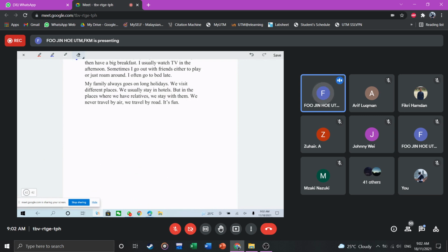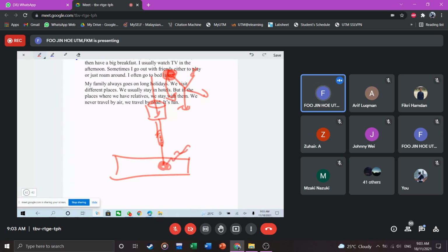Normally, you have a holder, you hold a drill bit, and you have the workpiece here and a handle here. You hold on to this knob and move it downwards, then you start drilling, and you can see the chips coming out, and in the end you will form a hole.